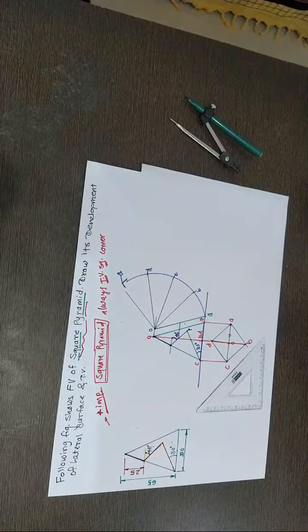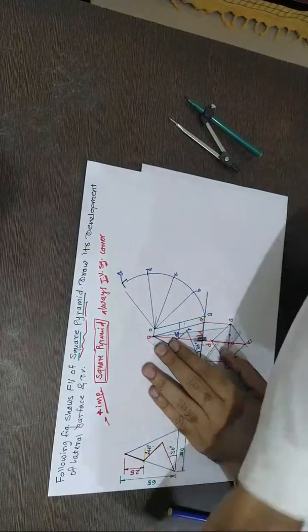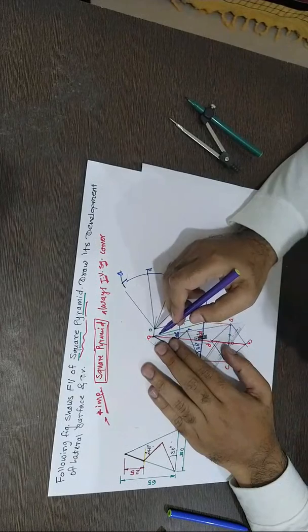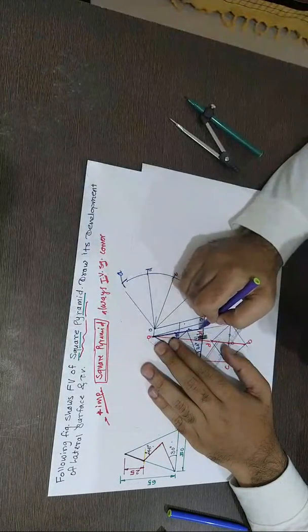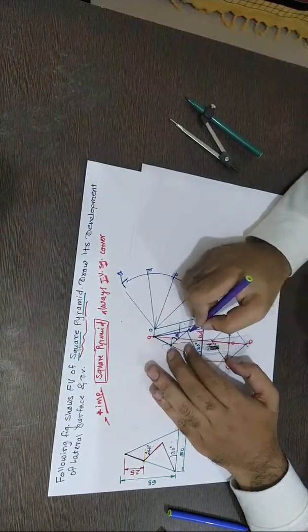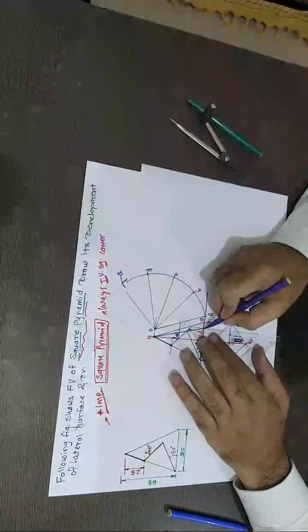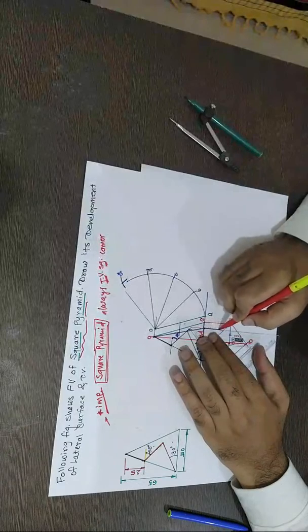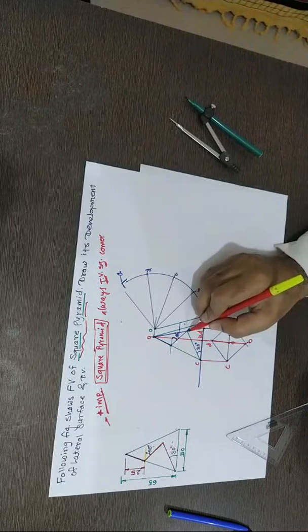Now I need to show how this corresponding edge is visible in the front and top views. So draw this slant edge representing this intersection point and transfer this point to the top view. Yeah, I should use different colors. Okay, so this intersection of the 45 and 30 is P, here.